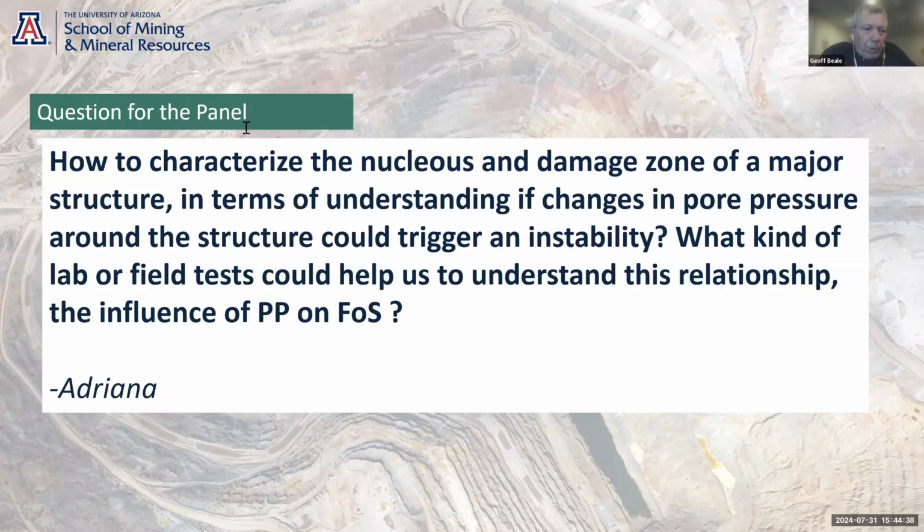Most structures will pinch and swell over quite small distances, and there's lots of underground situations I've been in where one heading goes through a fault and creates major problems and water inflow. You do an adjacent heading 20, 30, 40 meters away, and you don't even know the fault's there. So they can be very variable on a local scale.